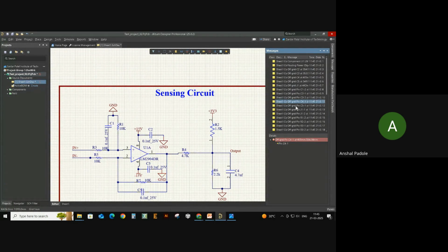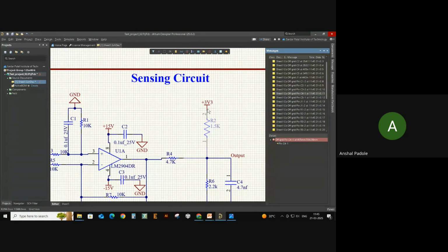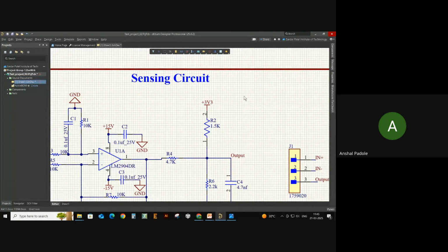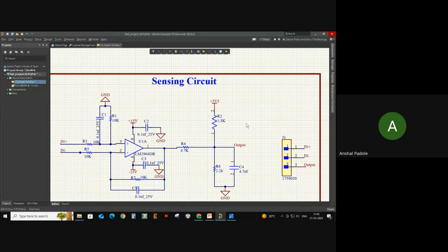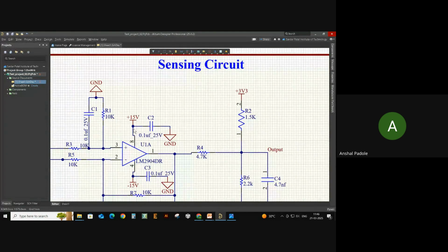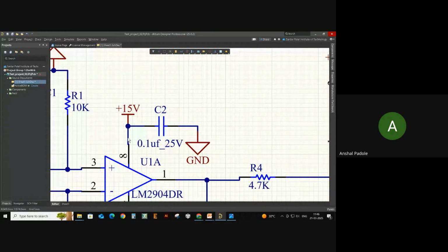For example, the one which says off grid. Off grid means the component is not matching the settings of your current schematic. So what are the grid settings? Here on the bottom left, you can see grid, and it is giving me 1 mm. So what does it mean? That I can move the component and wires with a minimum step of 1 mm. So here you can see the component which I'm pressing is moving by 1 mm. Each box is 1 mm.